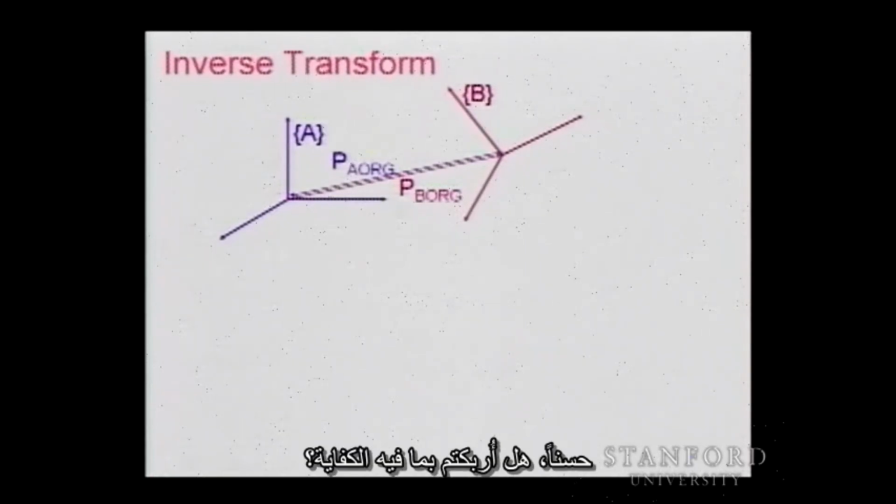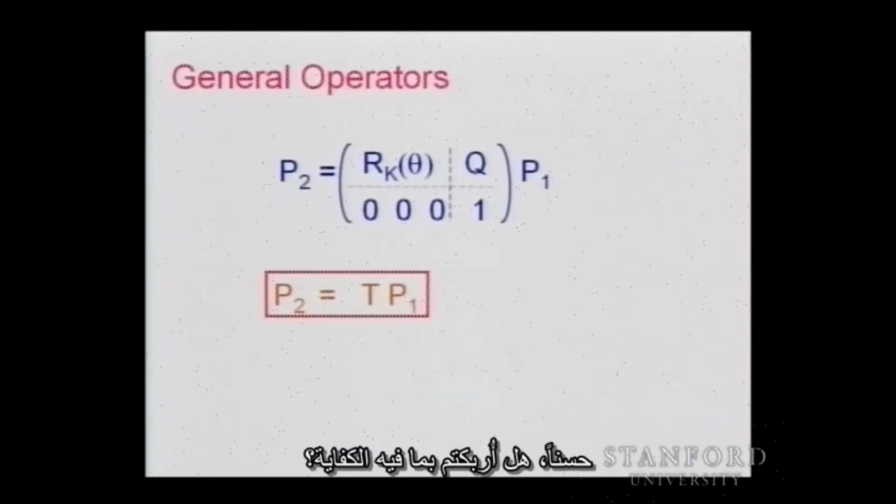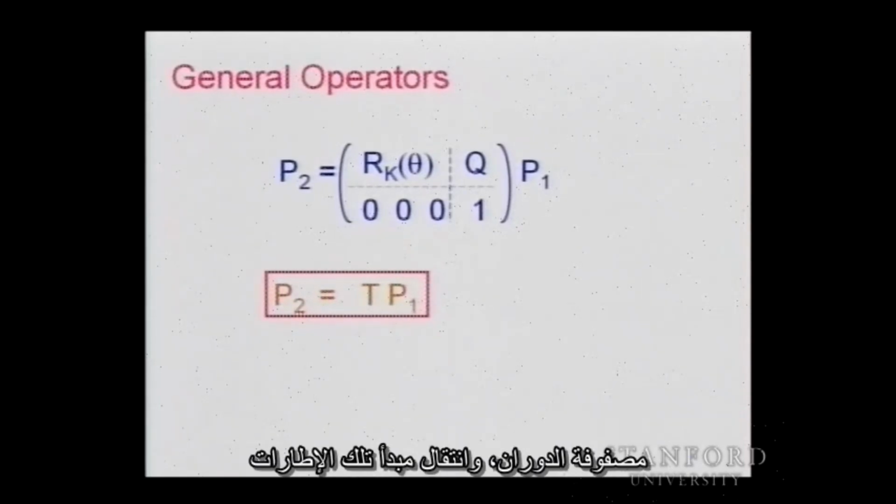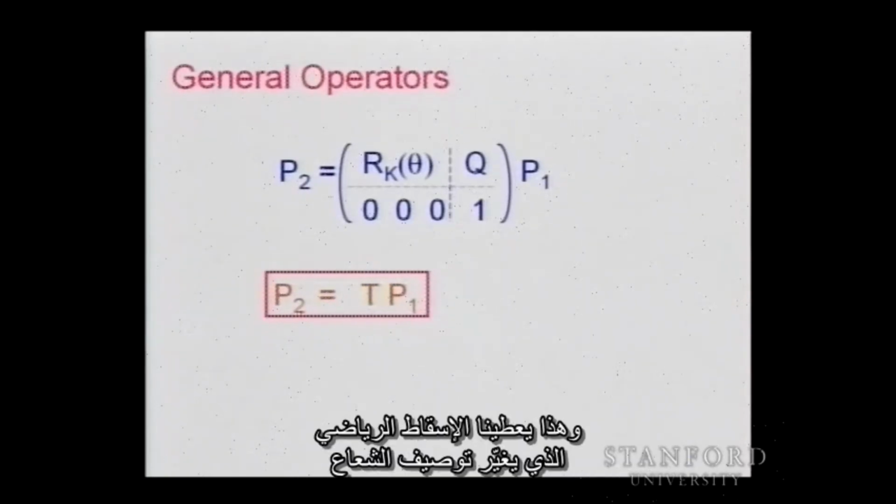Okay. Are you confused enough? Good. So two things. We saw the transformation. It is the same homogeneous transformation that has two components: rotation and translation. Rotation matrix, translation of the origin of those frames. And that can give us mapping, changing the description.